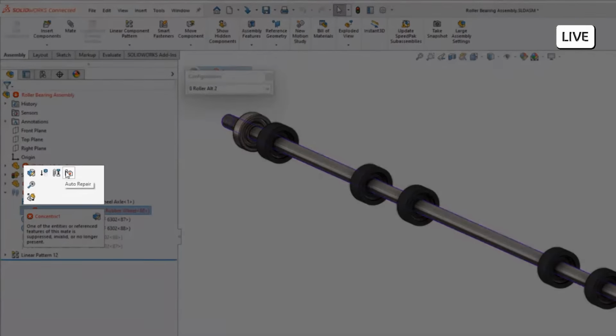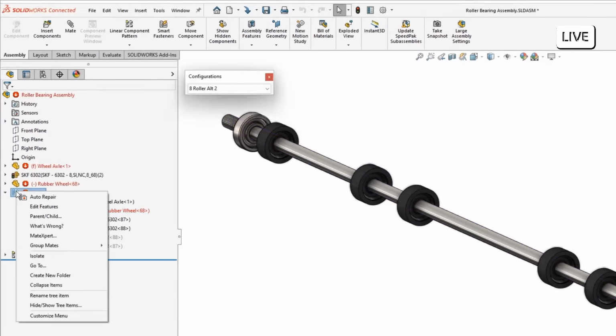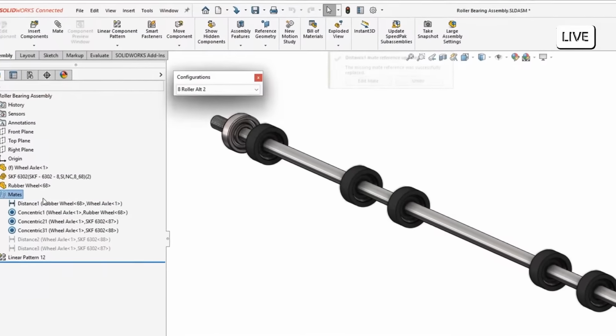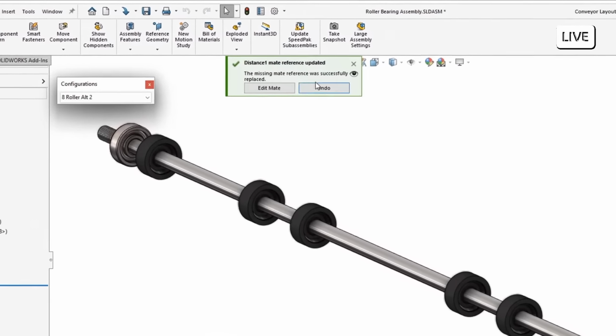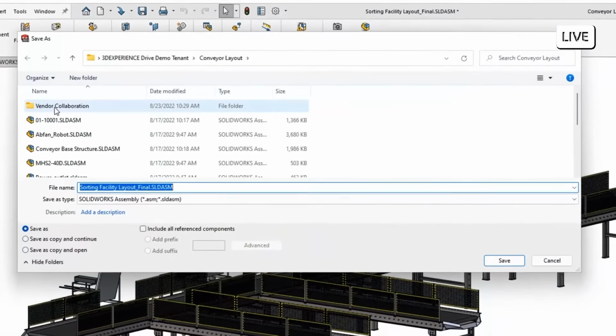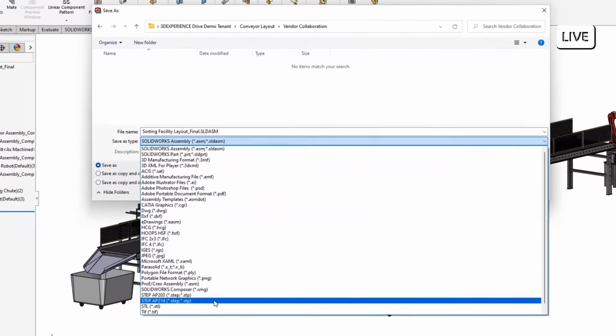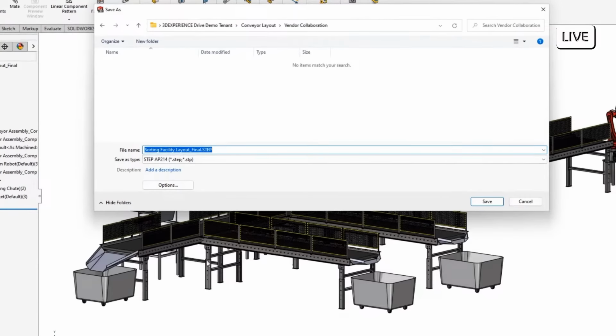It's unbelievable. For my clients that are working with large assemblies, sometimes they have to export their files as STEP to give them to companies who use another format. Well, large assemblies were really time consuming, and sometimes they would fail to export the STEP file. Now you can save the components of an assembly as a STEP file. It's just a simple setting in system options, press save, and magic happens.